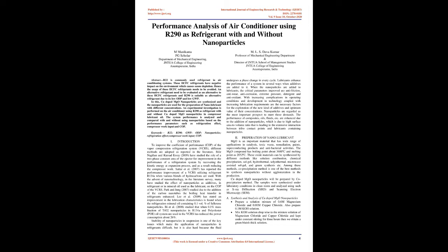Lee et al., 2009, have stated an improvement in the lubrication characteristics is found when the refrigeration mineral oil contains 0.1 vol% of fullerene nanoparticles. Bi et al., 2008, studied that when 0.1% mass fraction of TiO2 nanoparticles in R134a and polyester, POE, oil system are used in the VCRS, it has reduced the power consumption by about 26%. Stability of nanoparticles in suspension is one of the key issues which make the application of nanoparticles difficult in a system that undergoes a phase change in every cycle.